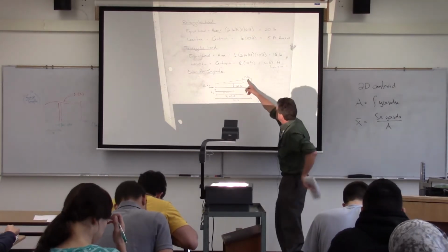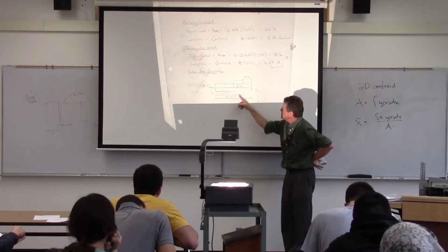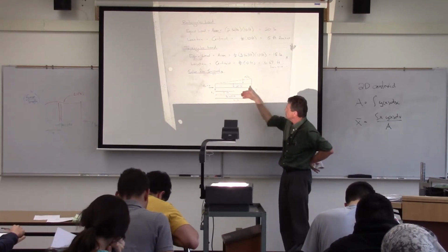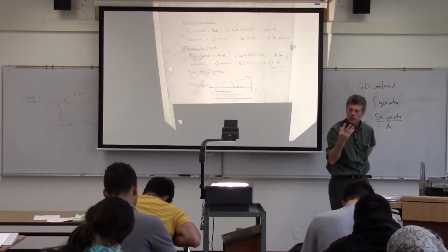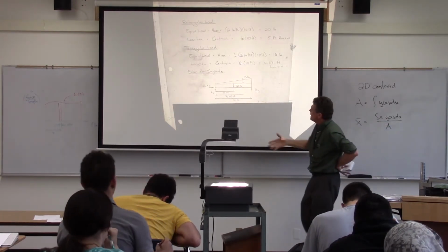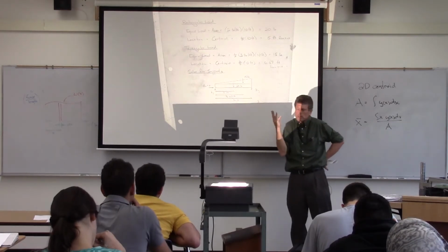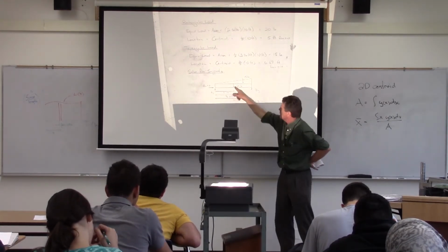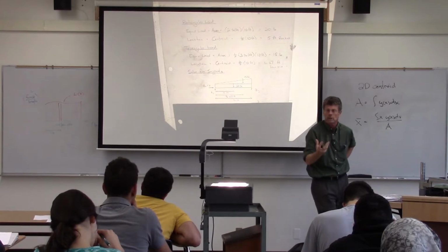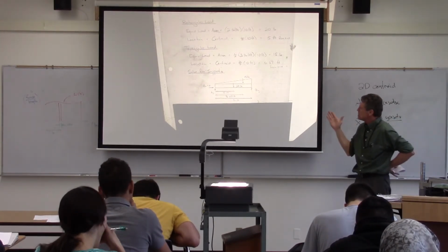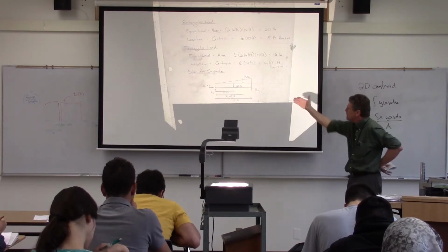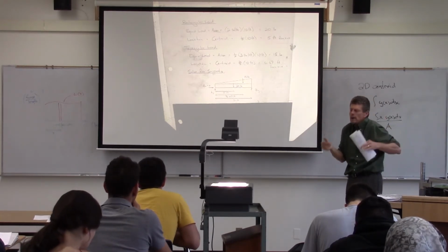So the location of my 15-pound is going to be 6.67 over, or 3.33 from here. The location of the rectangular portion there is 20. And then, again, like I say, I could use principle of moments and resolve that into, obviously, 20 plus 15 is going to be 35 pounds. So it's the same weight. But I don't need to necessarily do that step. I don't want to do that step because it's just simply two forces in my moment equation.